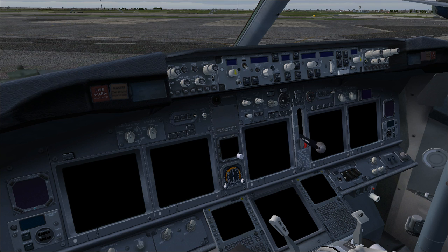We have the ability to select one or the other for printing information on our screens, and they must give the same information from the first to the second DEU. So the aircraft cross-checks the information between DEU 1 and DEU 2, and if there is a disagreement about the information or the values presented to us, the aircraft tells us by printing a number indication on the screens.